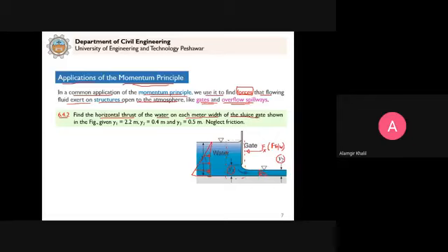So this results in this hydrostatic pressure diagram. You see that this will be a force acting on this control volume. This will be F1, and similarly there will be a force here. This will be F2. Now you can see that these are the external forces acting on this control volume that we have to consider in the momentum equation.